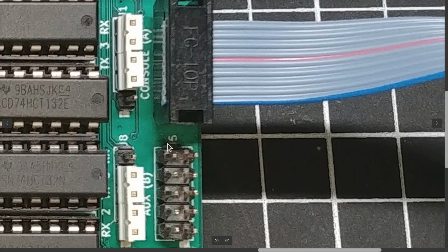Anyone who's done this back in the day knows perfectly well that you never, ever have the right cables, and your pins 2 and 3 are never where you want them. So I just gave up from the beginning and said, I don't care what cables you have. You either put the jumpers as shown here or down here. Moving them back and forth changes whether the transmit signal is on pin 2 or 3.